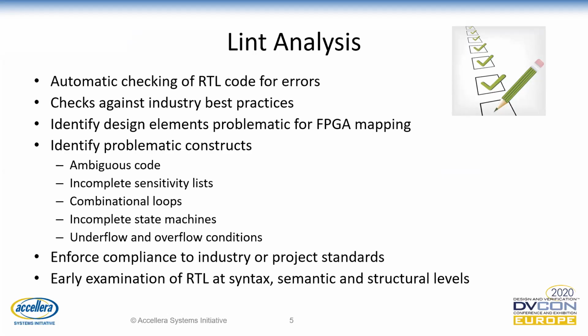So these are scenarios that sometimes simulation won't be able to find. So running simulation alone will not detect all these issues and that may result in a bad FPGA implementation. Lint analysis will ensure that your RTL conforms to industry best practices, as well as detect problem constructs such as ambiguous code, incomplete sensitivity lists, combinational loops, incomplete state machines, and underflow and overflow conditions.